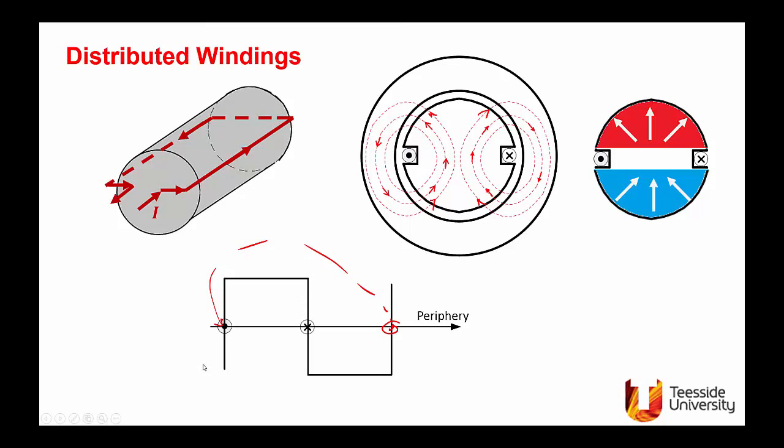So let me remove this annotation. Now, this is the magnetomotive force and flux density distribution, and this will have a first fundamental and harmonics. Of course, if it's a wave as shown in the solid black, it will have high content of harmonics. We need to reduce that, so we need to play a bit with the shape of this waveform. And what do we do?